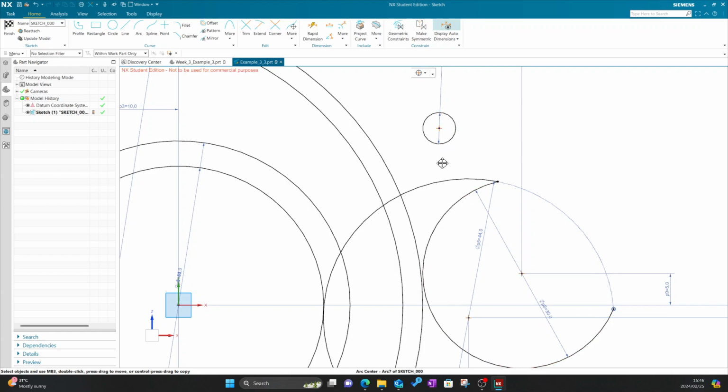So you can move this, or you can click on it. Let's move it first. The little image it displays now, or a symbol, shows for when the circles are coincident. So it automatically detects the coincidence of the two circles. So I'm just going to leave it there, and you can then see there's a tangent constraint between the two circles. Now you also want a tangent constraint between the circle and this curve.